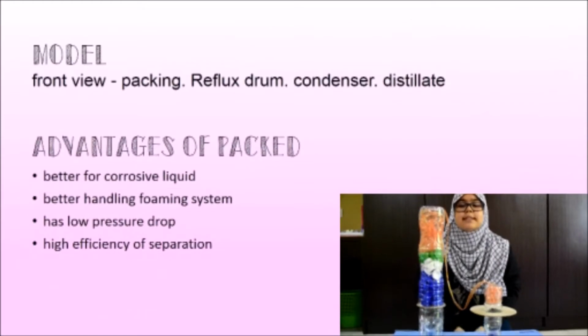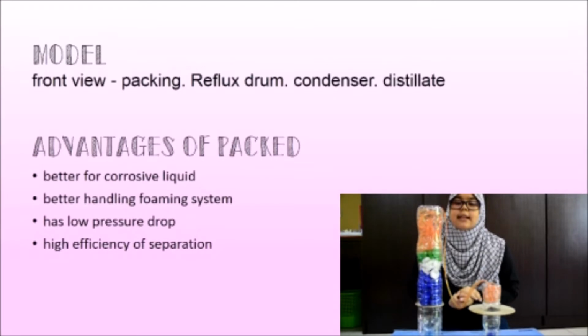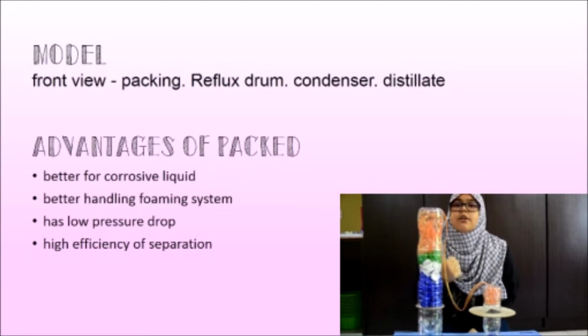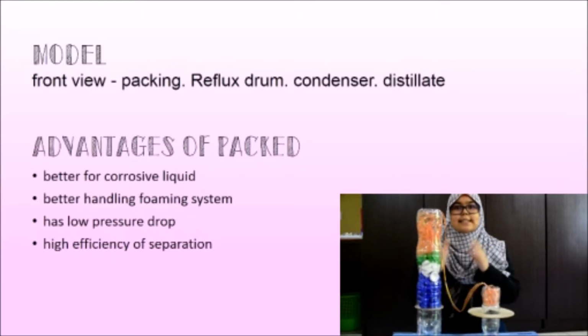Our group has chosen the packed distillation column because it has a lot of advantages, such as, first, it is better for corrosive liquid, it is better for foaming system, it also has a high efficiency of separation, and lastly it has a very low pressure drop that reduces the cost in the industry.